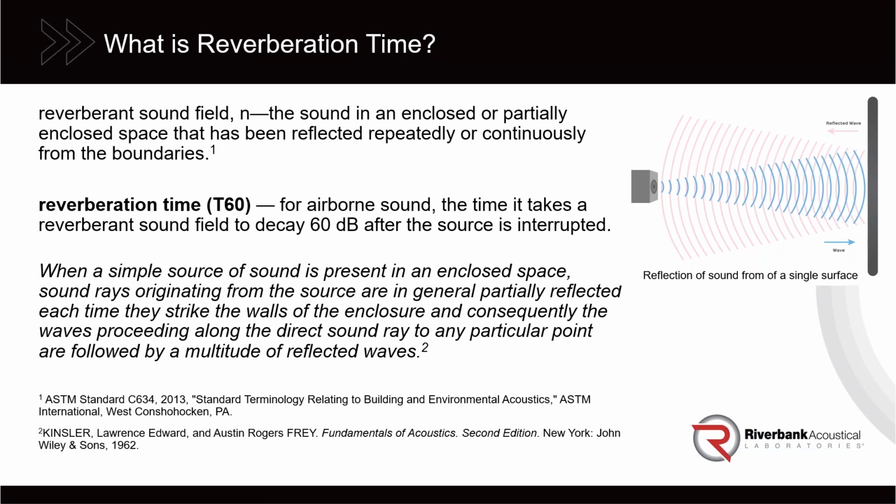So with the NRC classification and with ASTM C423, the fundamental phenomenon that we're concerned with is reverberation time. This is measured in terms of time. It's the time it takes a sound field to decay 60 decibels after the source has been interrupted. So if you are running a steady state signal and you cut that signal, the time from when the input source stops till you can't hear it anymore, basically, is the reverberation time.